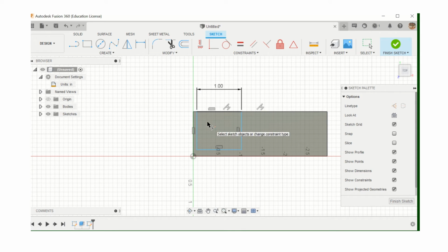And the moment I do that, you'll notice that it shifted up like so. I want this edge down at the bottom to be collinear with that, and I want this to be collinear with the back. And what that's done is it's made my rectangle perfectly line up with the box that I already had. I had to learn that the hard way by trying to make it line up perfectly, and I couldn't. And that's all I need for my second sketch.